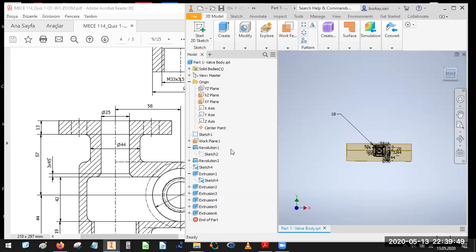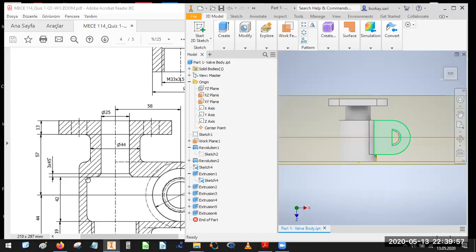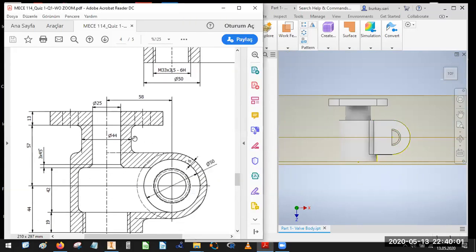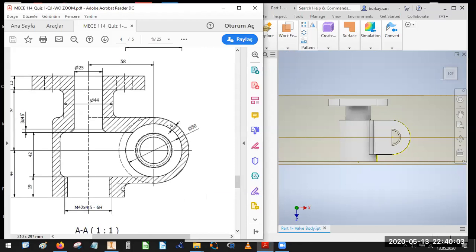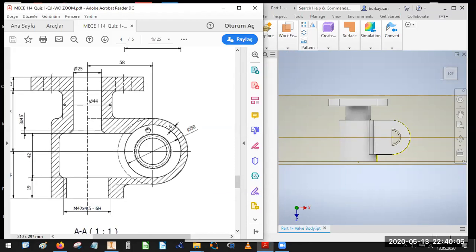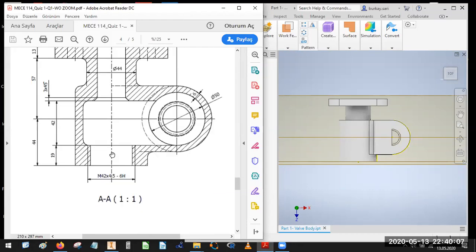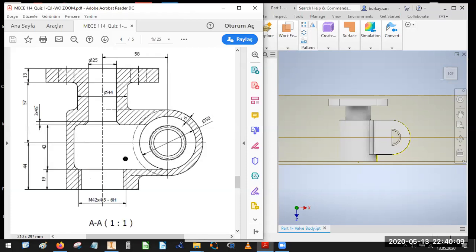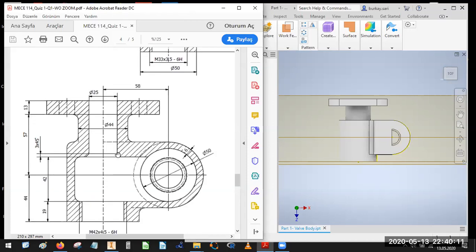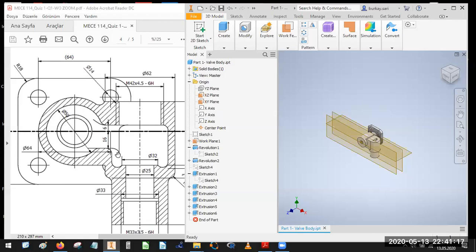These are the points which I have. Okay. We have the fillets on two sides. All the fillets are 5 millimeters. Here, what I'm going to do is clear inside where I see here. Let's first make the holes, then we clear the cavities.